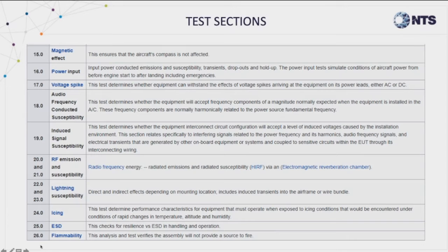It would be kind of a coupling type test where you would wrap your I/O lines and simulate an electrical field going through the wire, and how does that couple onto your I/O lines. Also a magnetic field, how that couples on. And then there's also a voltage transient, we call it induced spikes test, where you chatter a relay to show if there's a relay chattering on a power line or on a line next to your I/O line. Does that couple onto your line?